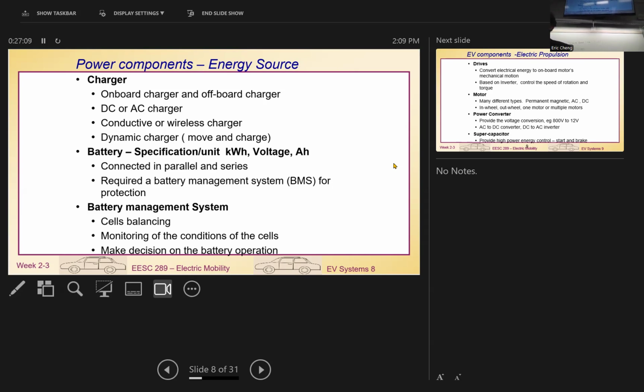But even though it's the same kind of battery, when they are manufactured, because of aging effects or other parameters or leakage, or some being close to this wire and some further away from this cable, the charging rate or the aging may be slightly different. So they may not equal the same voltage all the time if you put them in series. So that's the issue.